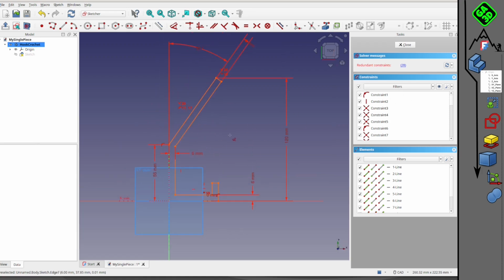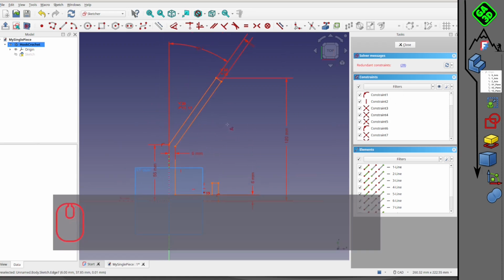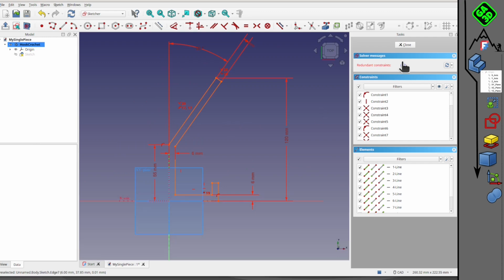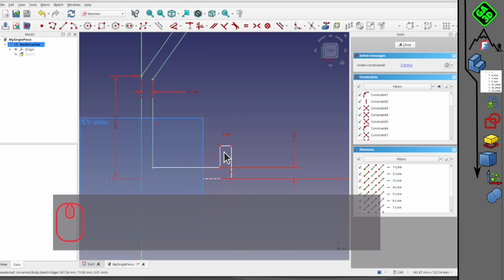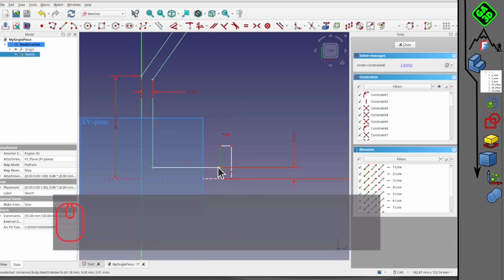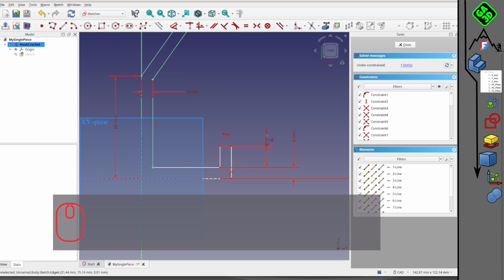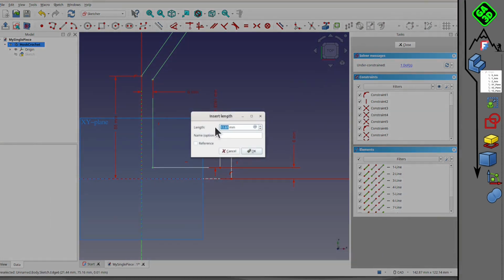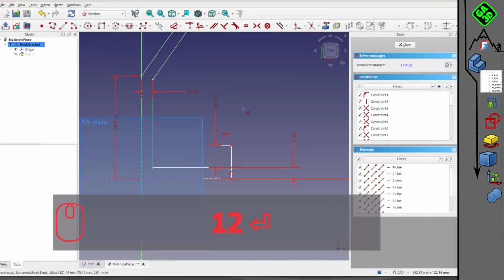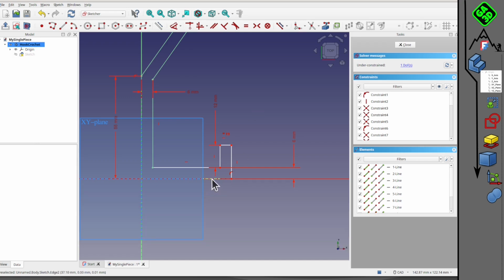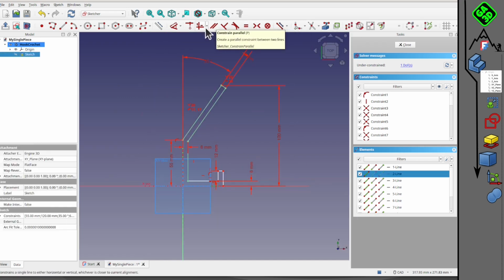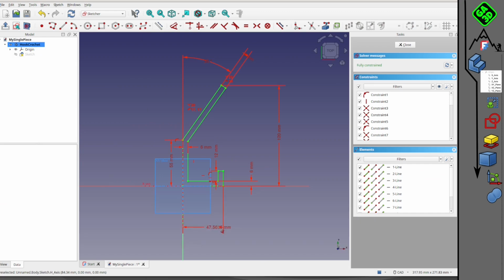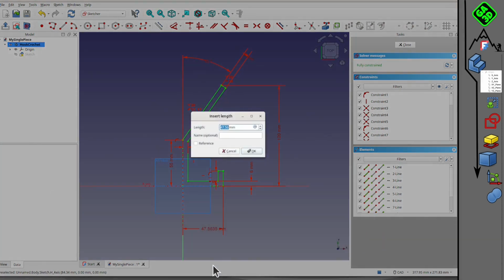And the total length here, we select this segment, and I want it to be 50 mm tall. There you go. So right now you see my sketch is green. It's all green. It means everything is fully constrained. It appears here: fully constrained. So that means everything is well defined. There is no longer any degree of freedom.